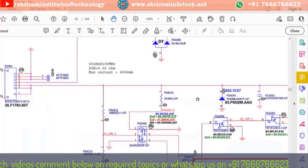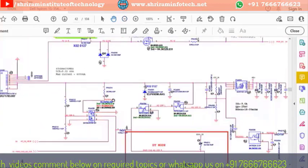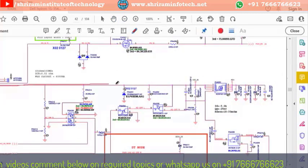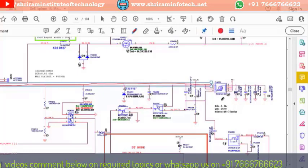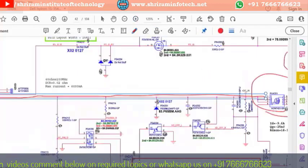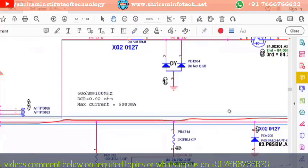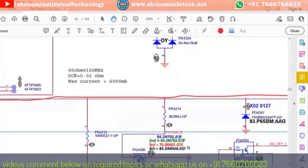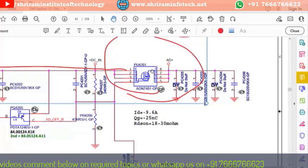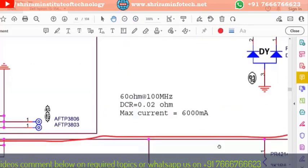Then my voltage will travel from here, like this. From the adapter, 19 volts will travel from here, and here is the first MOSFET. This is my first MOSFET. The MOSFET location is PU4201. And this one is an N channel or P channel.